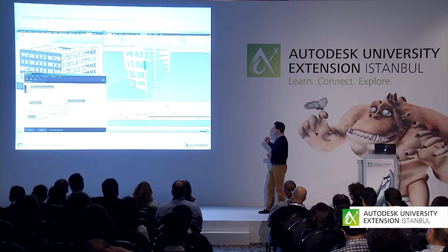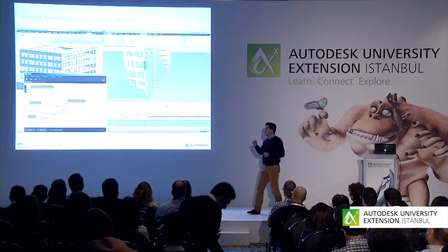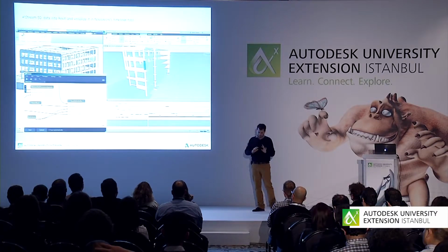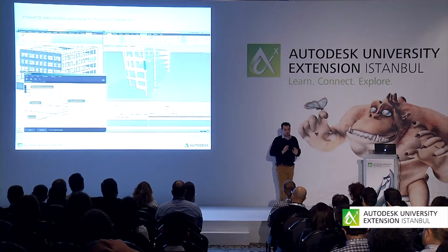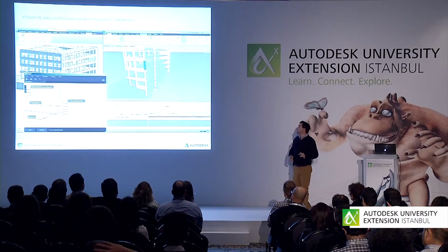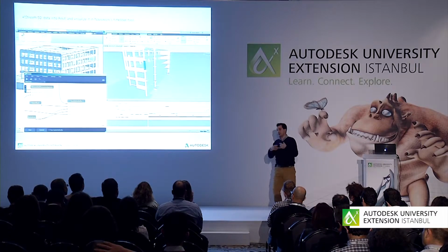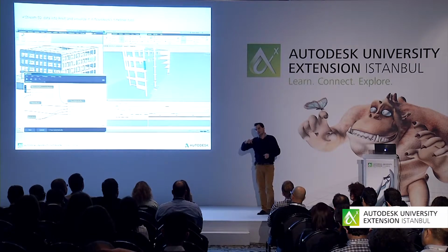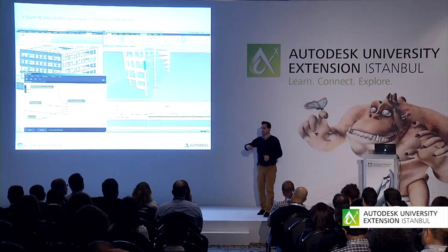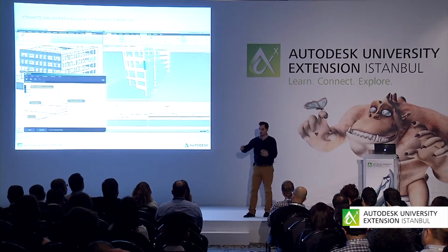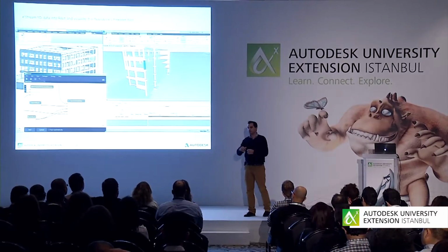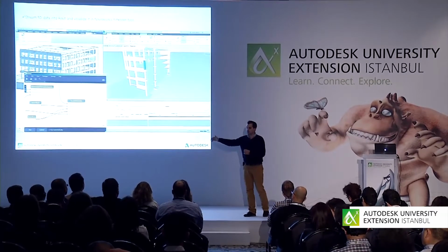What Dynamo does is, with a relatively simple script, you can stream into your Revit model data which can be described as 5D. So you can stream the order of appearance on the construction site, the sequence of pouring concrete, but also the time it will take.